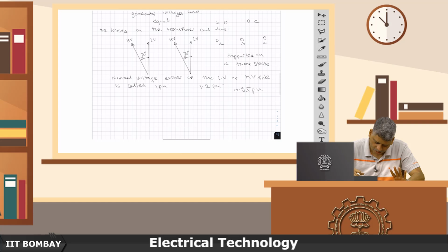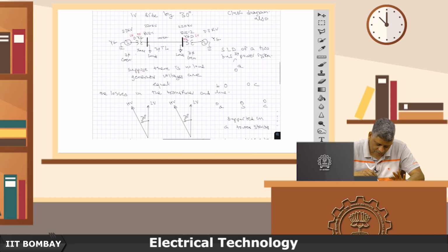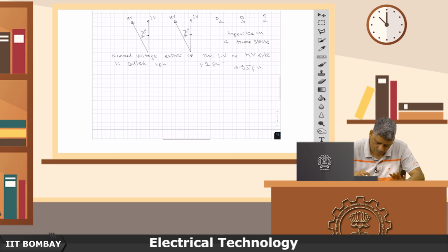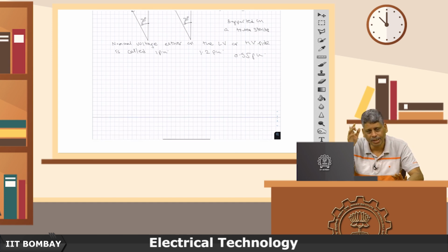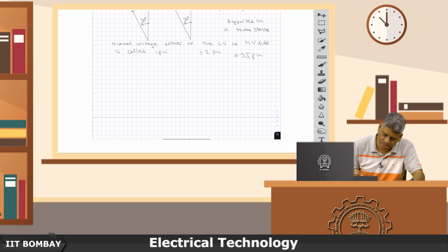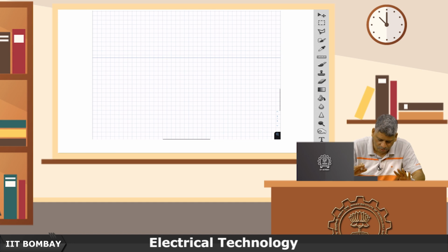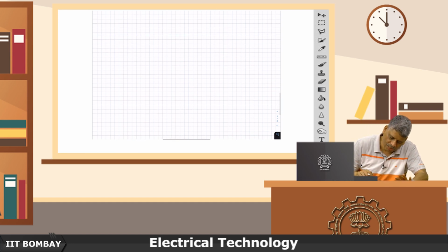So, if we keep interconnecting the transformers such that this happens, we make sure that under unloaded condition no circulating current flows in the power system, and this concept will be expanded in a power systems course. So, right now I will not expand this concept by taking multiple buses, a 4 bus system or a 6 bus system, and show it to you. So, we will leave this topic here and come back to the transformers.